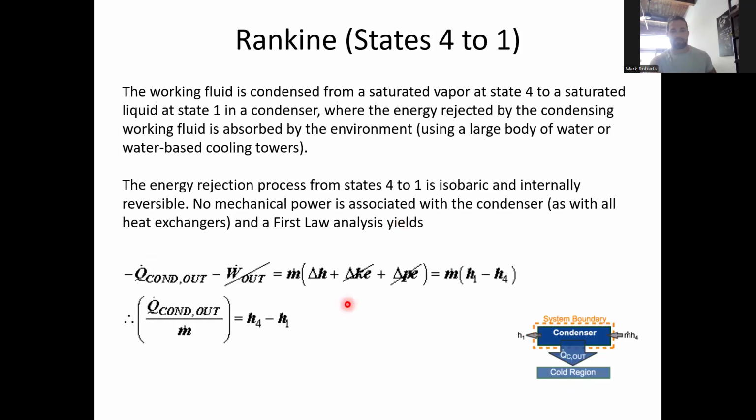And then the amount of cooling that's done. This term doesn't matter really because we're going from the saturated vapor to the saturated liquid. But we can see how much cooling is required in order to condense this stream. And this is only useful to determine how big the condenser needs to be, what the conditions of that component are.